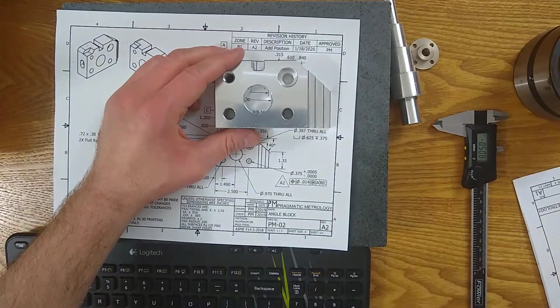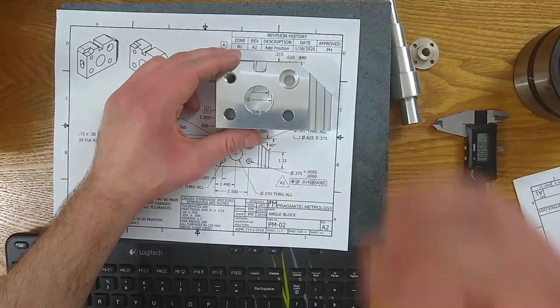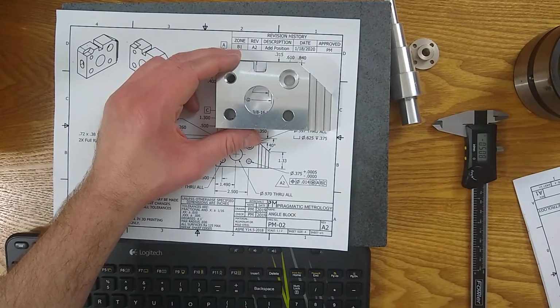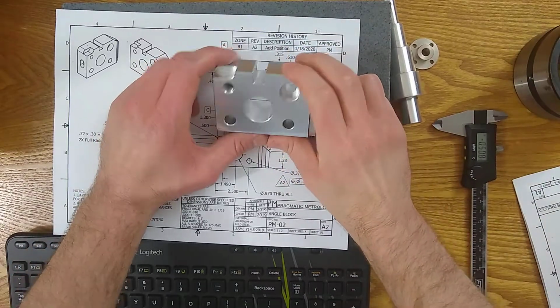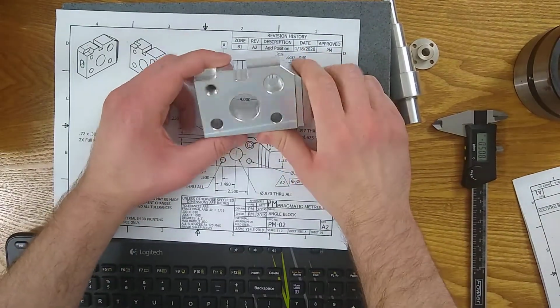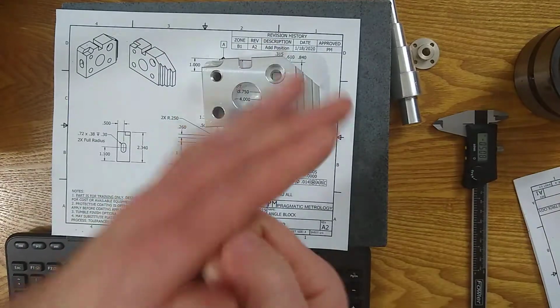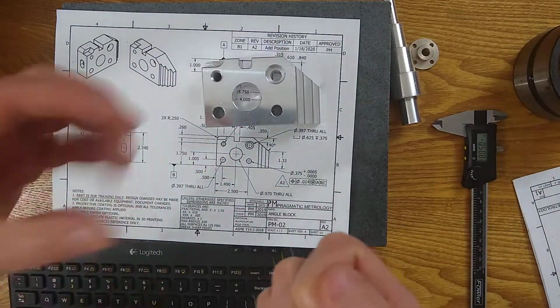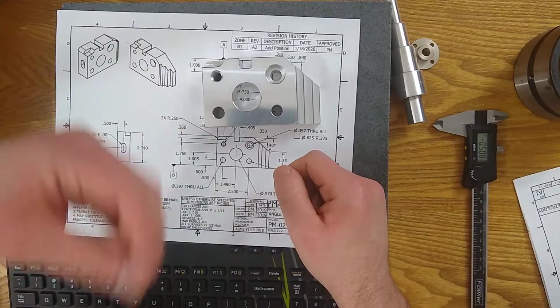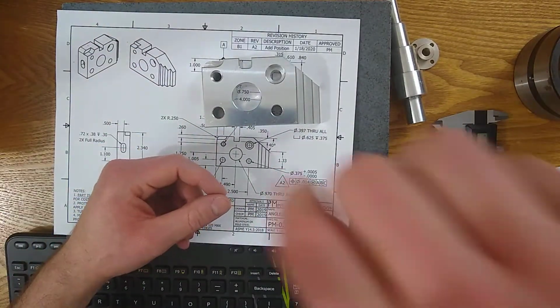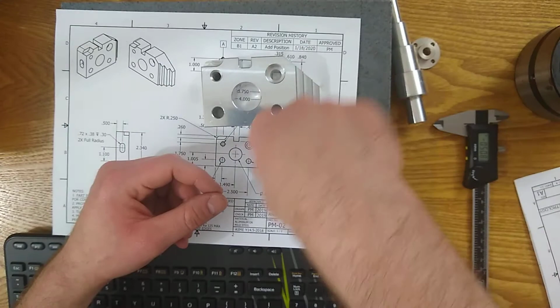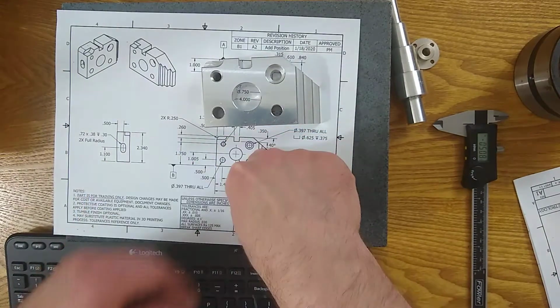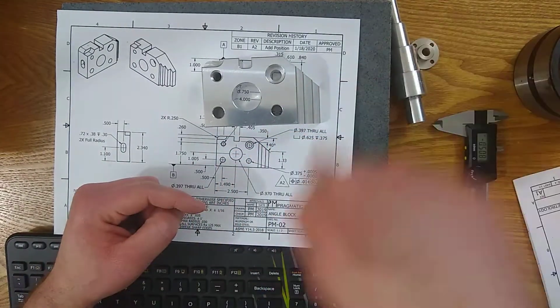And then last one, verify your depth with a ground flat bolt and caliper. What that looks like is basically you take a bolt and grind it flat. Whatever the manufacturer, there's usually a nose on it that you want to grind flat. When it's ground flat and it winds down, it'll stop at the bottom thread.